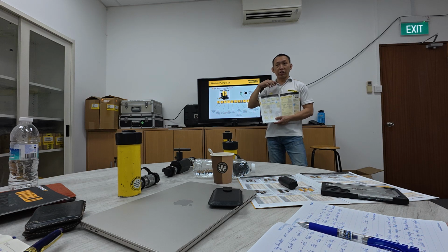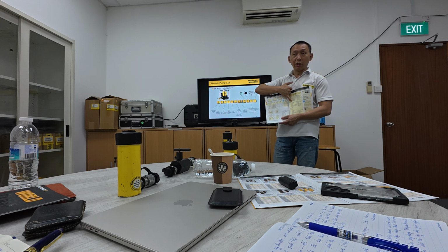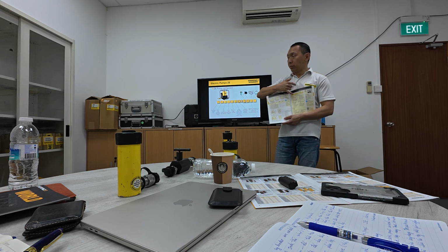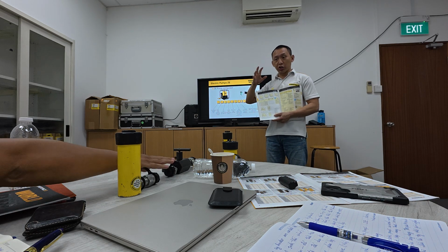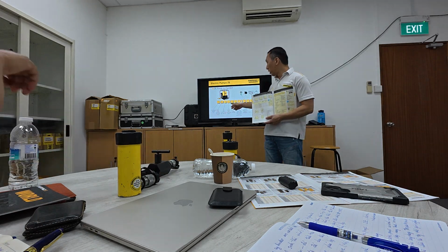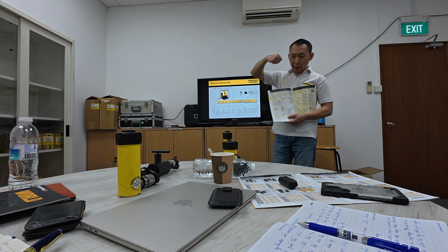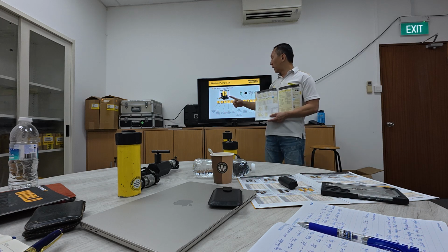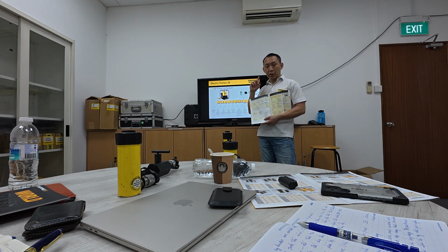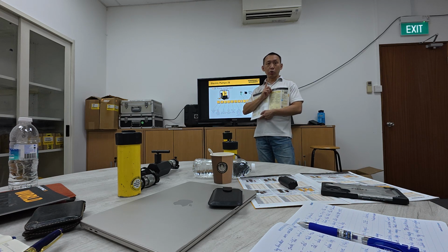For example, if you use a double acting cylinder, then you probably use a 4-way 3-position type of valve. If you use single acting, then probably you have a 3-way 3-position. And of course, if you use a dump valve, then it will be a 1. Dump valve means after you press, let go, and it goes back to 0. So this selection is based on the application and the type of tool you use.